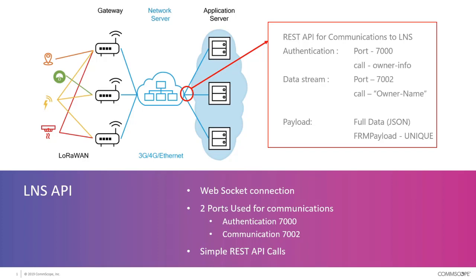But as we start looking at how we onboard the sensors and how we use the sensor data, we have to now bring the data out of the LoRa network server and into our application server. So we provide the data using a standard REST API format, and there are a couple of things that are used to authenticate and provide connection and authentication for the devices within the network. So the first thing is that on the application server interface, you have to connect to the WebSocket and to the interface and provide user information about who and what sensors you're specifically interested in.